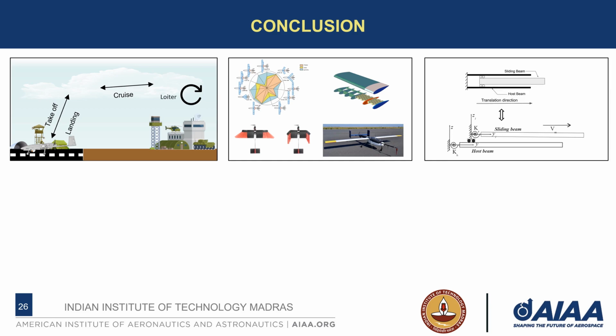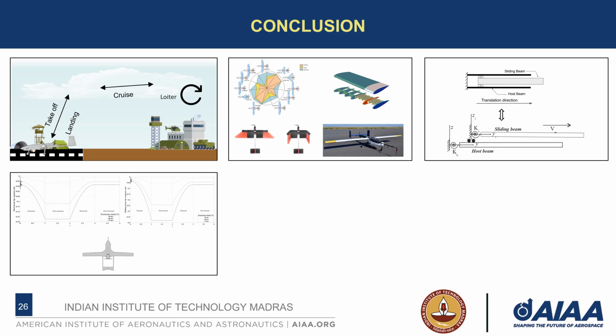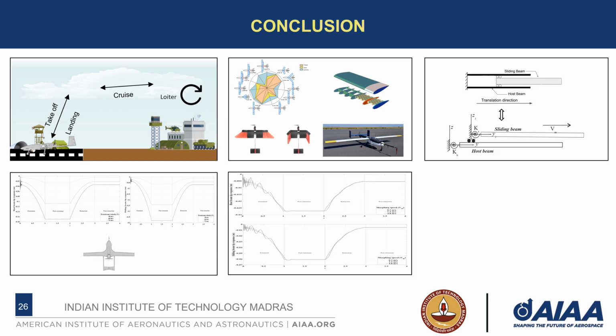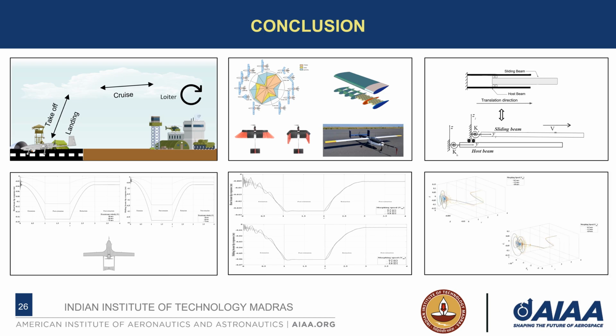A coupled double cantilever beam model is developed to mathematically model the telescopic morphing wing mechanism. The effect of free stream velocity on the telescopic wing is studied for various morphing phases. Similarly, the effect of morphing speed is also studied here. We have also observed the phase portrait and observed that in the post-morphing process, the response trajectory is attracted by a stable limit cycle.